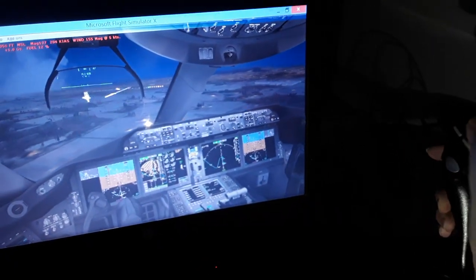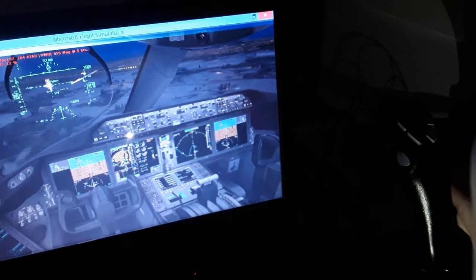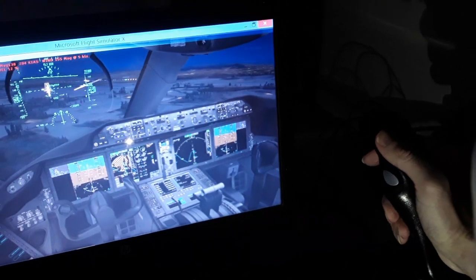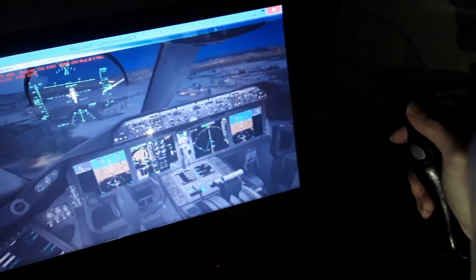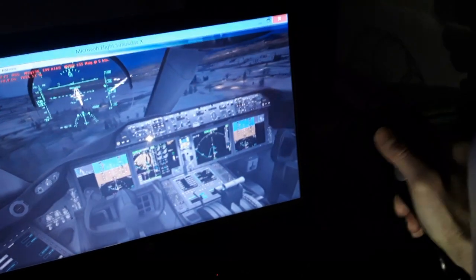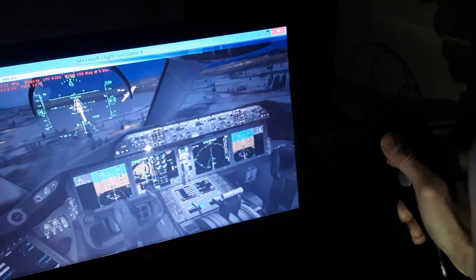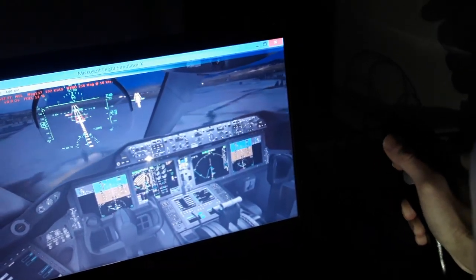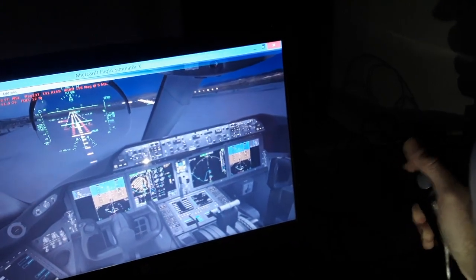So we are aligned, very nice, very beautiful alignment, very professional. Use a little bit less maybe thrust over here as we are descending. Align with the rudder pedals. We have some wind, side wind component and some wind gusts. So we align with the control wheel, ailerons and spoilers, and also rudder pedals. Align with the center line, also with the lights and the LSZH localizer.